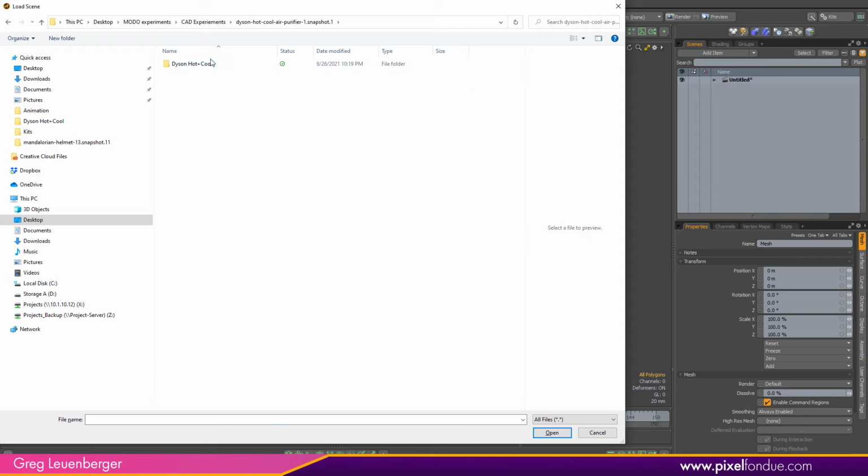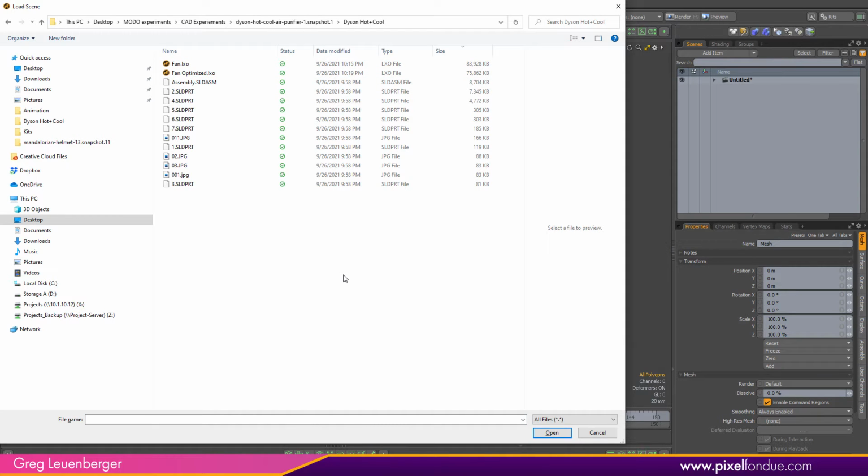So now this is more typical. Ignore the LXOs there for now. Typically, if you get a SolidWorks assembly from a client, you get something with a lot of these little part files, and often they're not named nicely like this, numbered, or where it says assembly. You see this new extension here, SLDASM, that's SolidWorks assembly. If you get something big, like a big medical device, you may have hundreds of parts in there. Every little screw and bolt and rivet and washer and rubber ring is a different part. And you may have multiple assemblies because assemblies can nest their references.